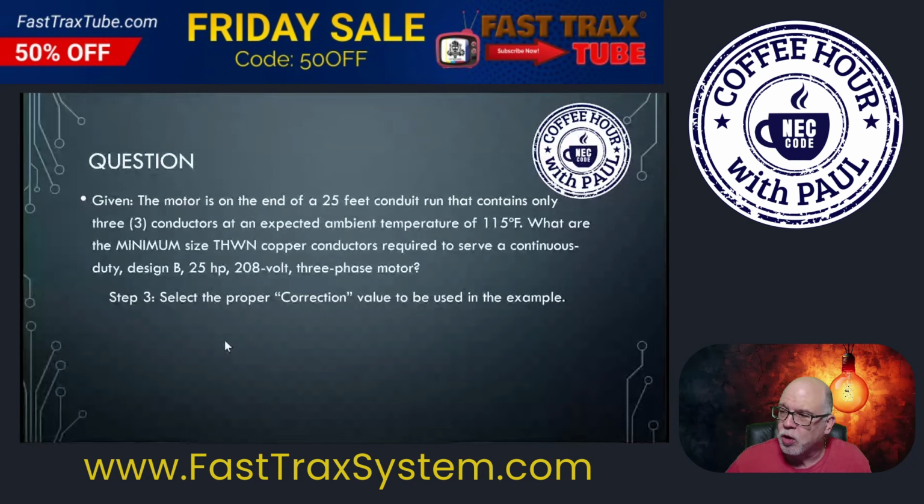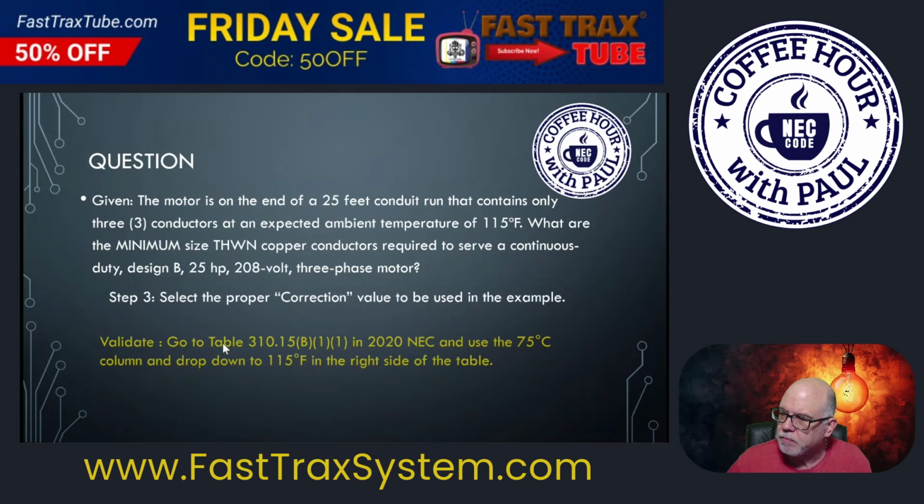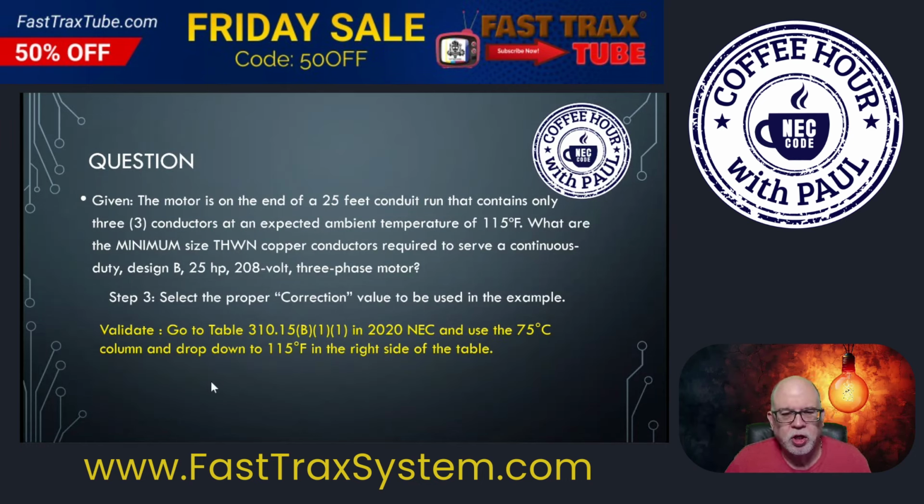Okay. All right, so we're looking at 115. What we're going to do is go to table 310.15(B)(1) in the 2023 edition of the NEC, but it would be 310.15(B)(2) in the 2020 edition. Doesn't matter. It's going to be the same location. So let's go do that.